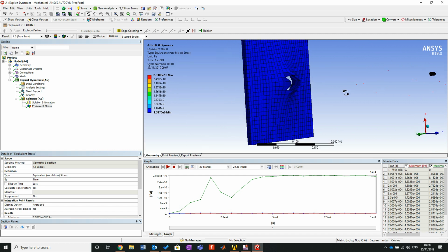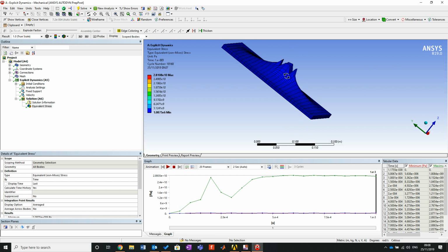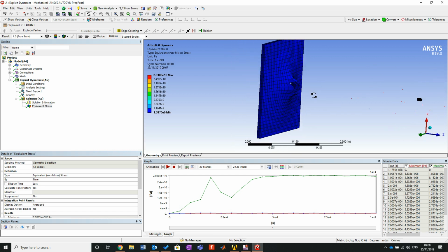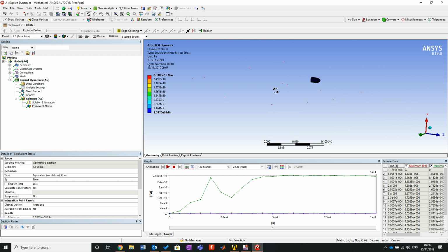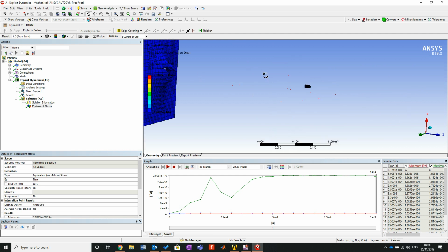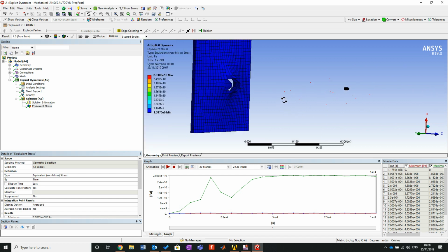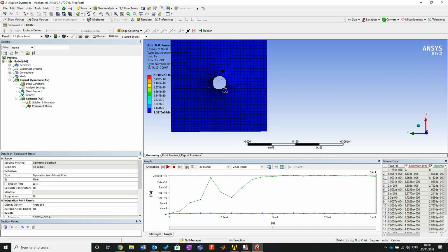The deformation, you can almost see the material heating up and trying to turn into debris, but the elasticity of the material almost holds it together, so it becomes massively deformed. You end up with deformation across the plate exactly the same way. I was actually quite impressed, to be honest. These here, now some said before, why are there red dots? These are eroded nodes. These are nodes that have broken away from the actual sim, so these would actually fit round here.